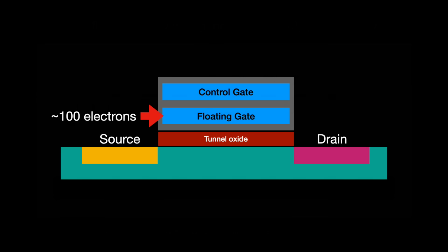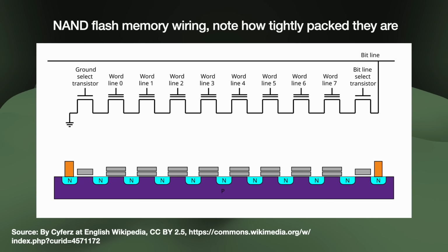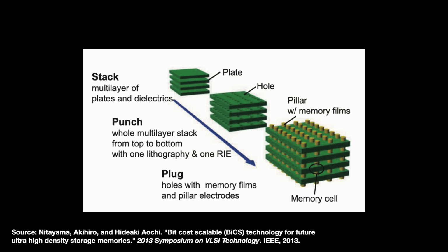These scaling problems are why the NAND makers switched to 3D NAND. You loosen the floating gates as technical requirements by resetting their sizes from 28 nanometers to 40 nanometers, but then stack them vertically to achieve massive storage numbers. 3D NAND is made in a parallel manner and very cool, in some cases literally, but not a valid technical pathway for eFlash. Nor is it economically feasible for the chip designer to add what can be up to 10 additional masks to produce a wholly different transistor type onto the chip.